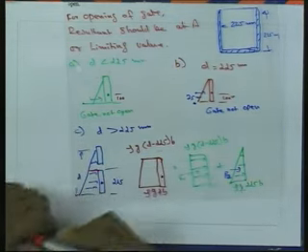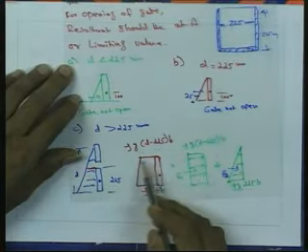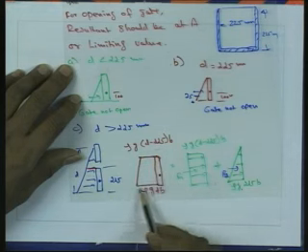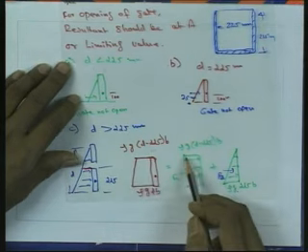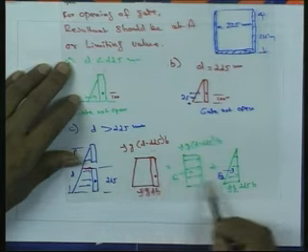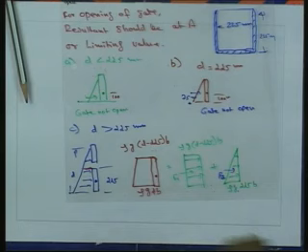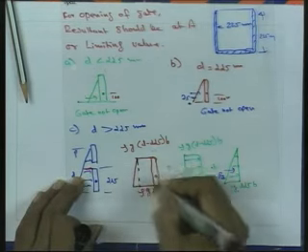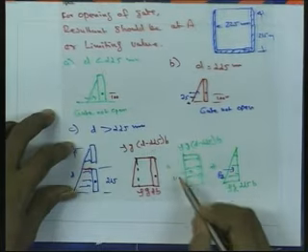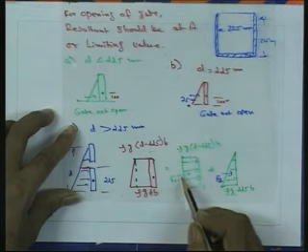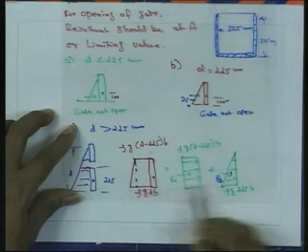So, for that we can draw the pressure distribution. This will be a trapezoidal pressure distribution like this, and here it will be rho g into D into B. We can split this into one rectangle pressure distribution and one triangle pressure distribution. So, finally this will be equal to F1 plus F2, where F1 stands for the rectangle pressure distribution and F2 is with respect to this triangle pressure distribution.